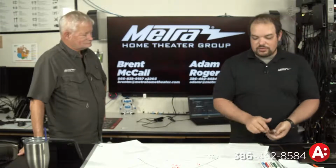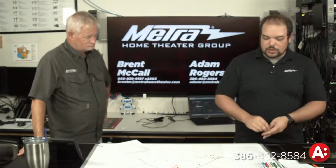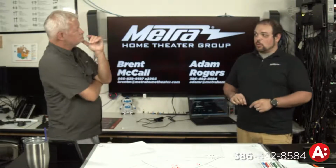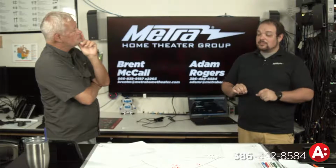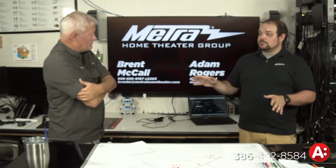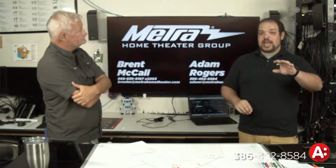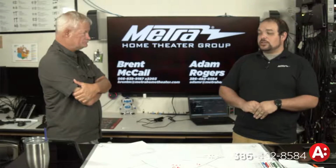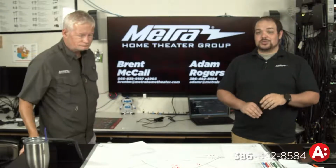Because if we now have to send out, let's say we use 4PPoE, where we have a max output of 100 watts at the port, that means that device is working all out if it's having to push that much power across it. To max across the port. Exactly. And so that's going to add a lot of wear and tear to your system. You want to go ahead and decrease that. And it will die earlier. It will. You want to decrease that as much as possible, and it starts with the infrastructure.